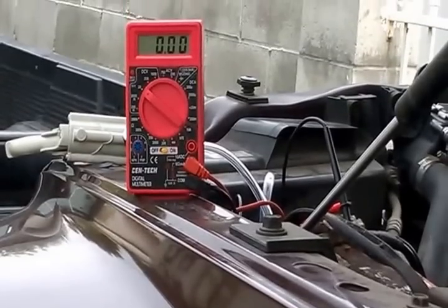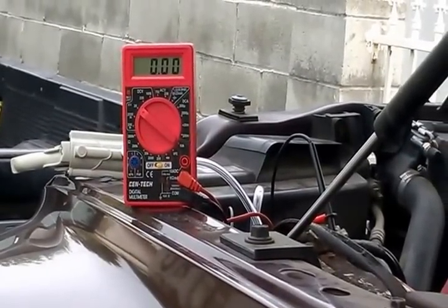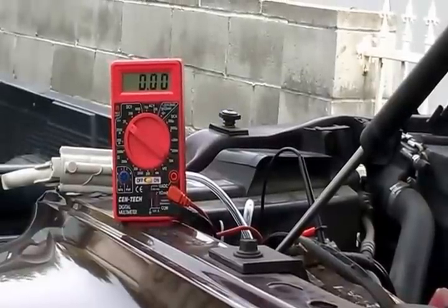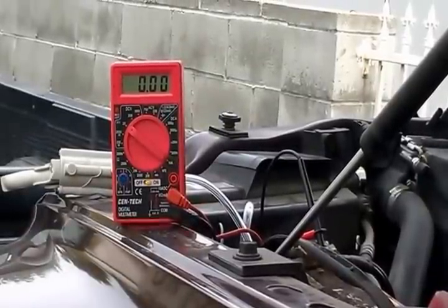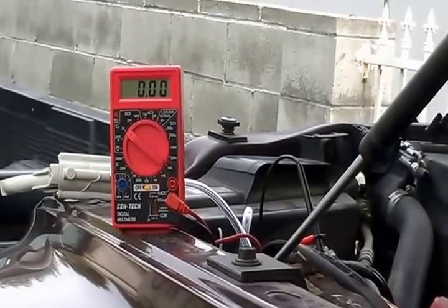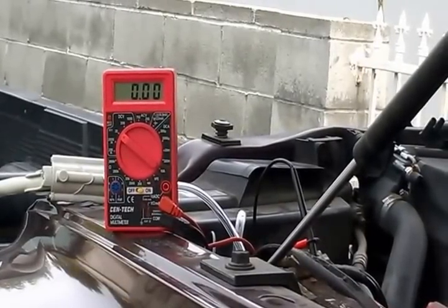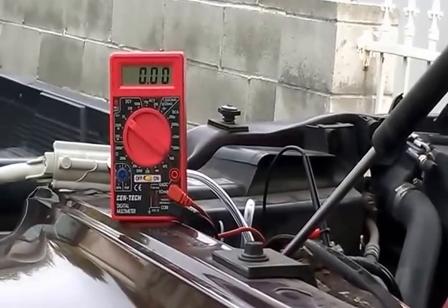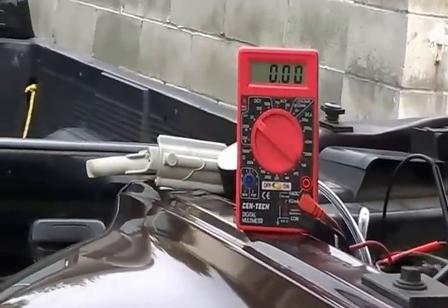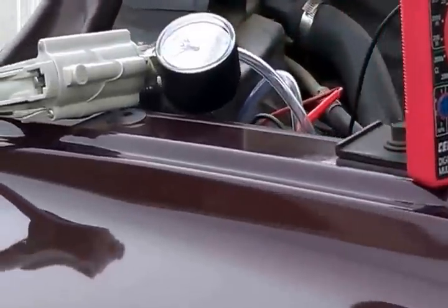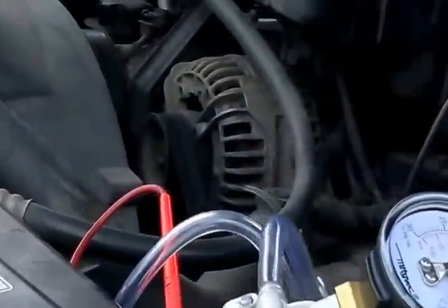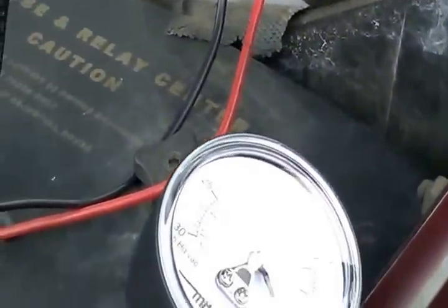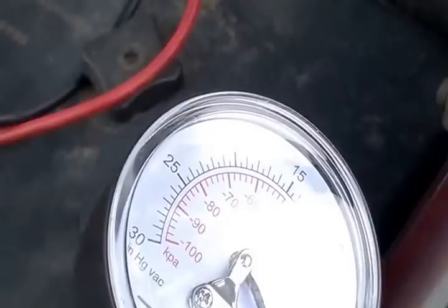For example, if this Evap purge solenoid circuit was not pulse width modulated, this ground side should have been 100 millivolts or less. But since this circuit is pulse width modulated, this voltage is going to be higher than 100 millivolts. The next step now, I'm going to show you guys the vacuum test. I already showed you the electrical side of this. Now the vacuum test, and I'll show you guys how a good working Evap purge solenoid should hold vacuum.